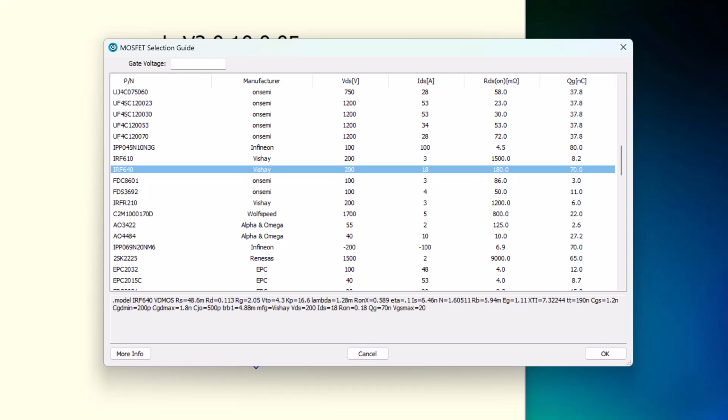This is not the simple level equals 1 model you may know from introductory courses. That one is far too idealized for power devices. VDMOS is essentially level equals 1 plus a body diode with reverse recovery plus a nonlinear Miller capacitance CGD that collapses with VDS plus separate parasitic resistances on the drain, source, and gate. In other words, exactly the effects that actually matter in a power MOSFET.